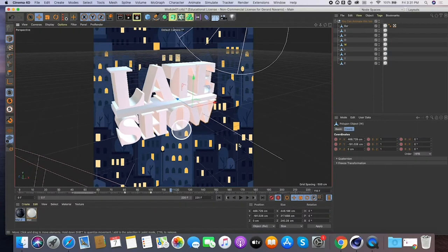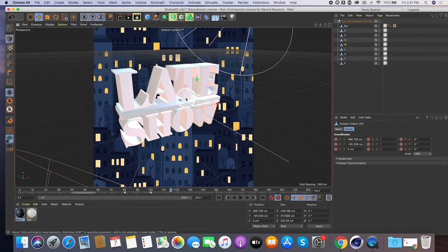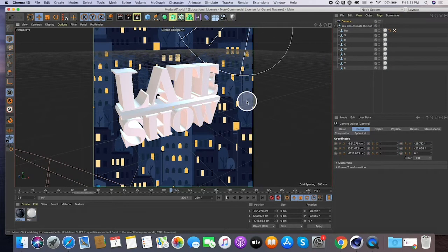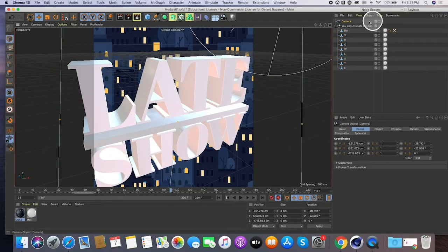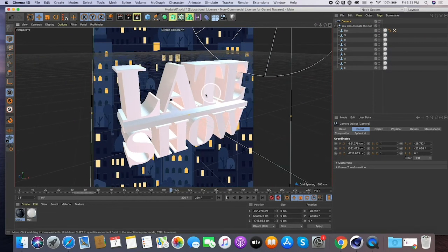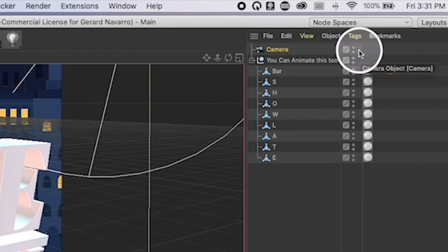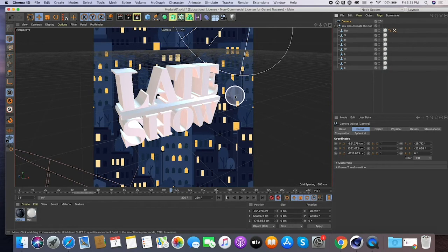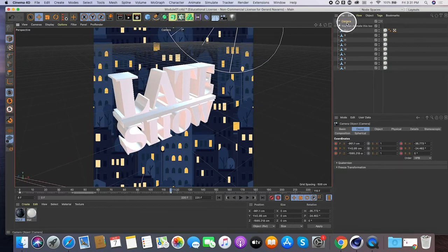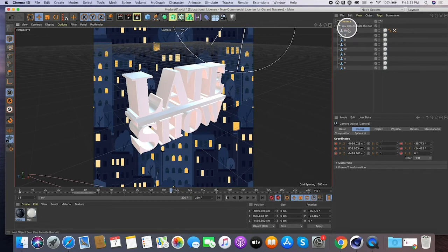So the next thing we need to do is also animate the camera. So to do that, you need to create a camera from your Cinema 4D scene. So to do that, here at the top, we can add camera. And then to switch this camera to the perspective that you are looking to, basically, you just need to select it, and then here, as you can see, the square icon, once you click this, the view that you're seeing right now is your current camera over here. So once that is selected, you can now add keyframes to this camera.